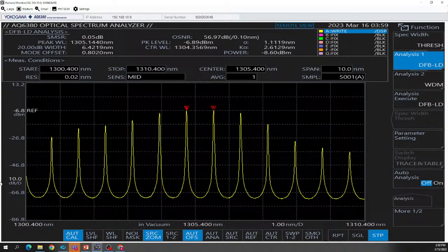So generally, as another side note, our OSAs are fiber based. So if you have a signal that isn't fiber based, we do have a workaround that will allow you to essentially put light that is not in a fiber, essentially a free measurement jig setup is what it's called.